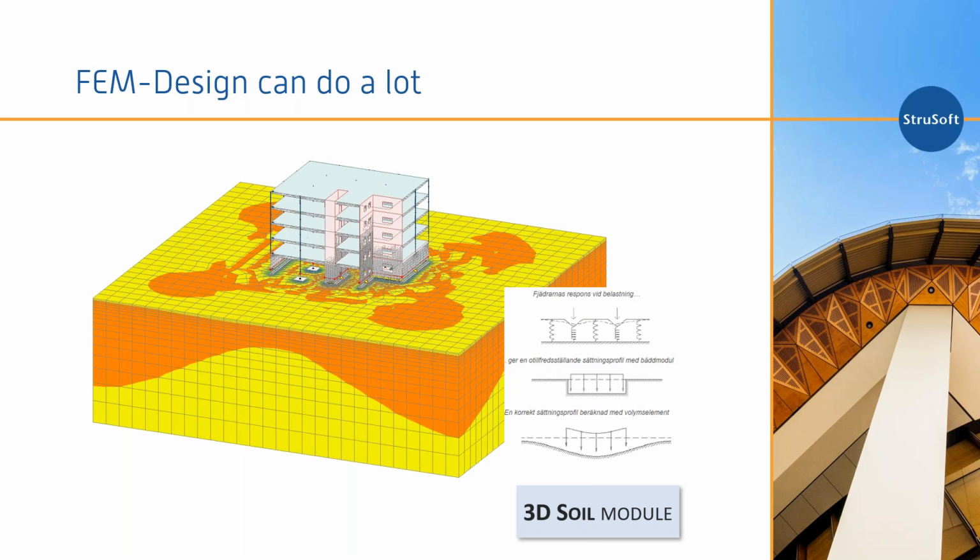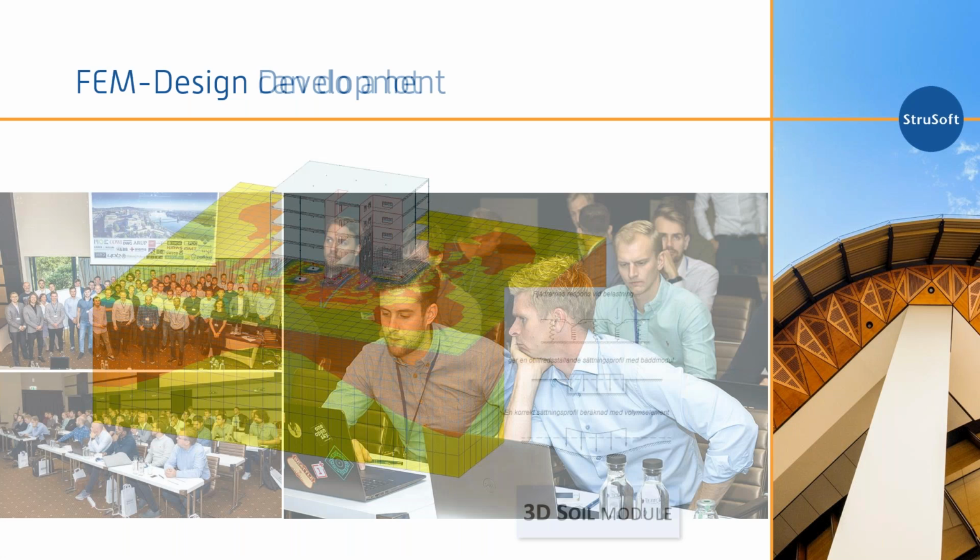It gives you a more realistic behavior of the soil and the structure together with the soil. It considers the soil as 3D finite elements, and it gives a much more realistic behavior than a bedding modulus model or a spring model. And you can study the behavior of the structure and the soil in one model.